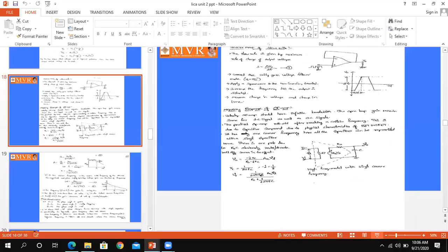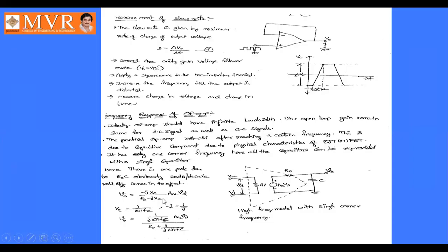So you can observe here, this is the circuit we are going to consider. In this circuit, the output voltage V naught is equal to minus jXC, where we consider XC as the reactance of the capacitor. So minus jXC times AOL into VD, this is the voltage source, into the opposite reactance, that is minus jXC, divided by the total resistance or reactance in this path, R naught minus jXC.